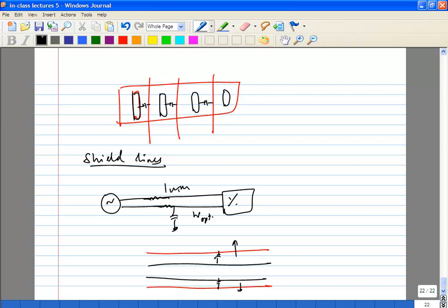Okay. Now again, if you space them out wider, then you're using up more area first of all. The second thing is, if there is something coming in from the substrate, this thing might pick it up. Okay, but yeah, you can only do so much with area.